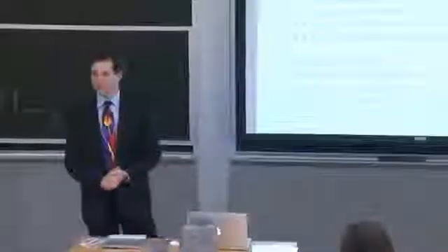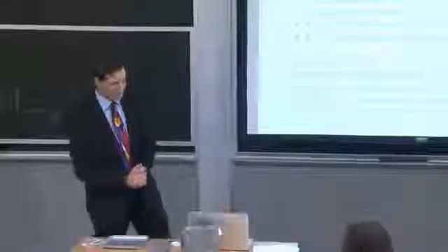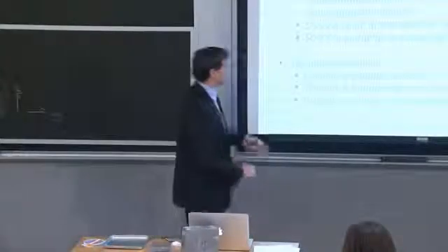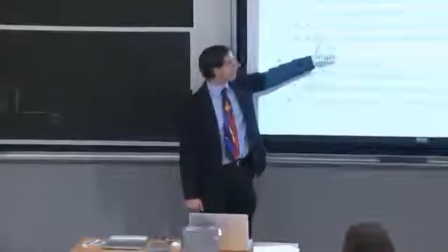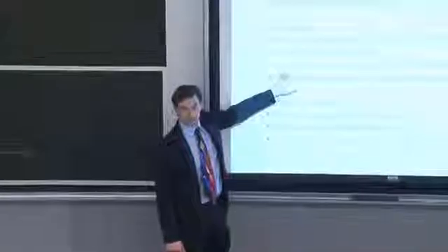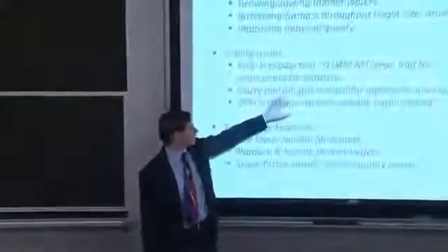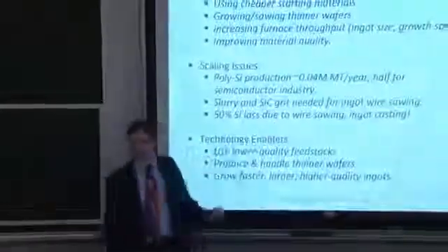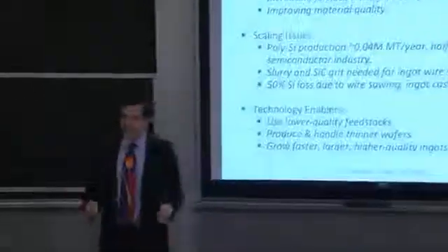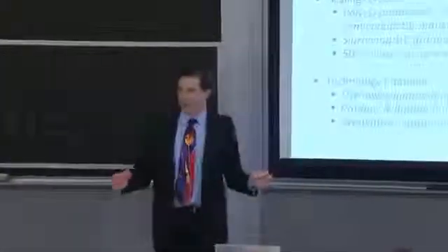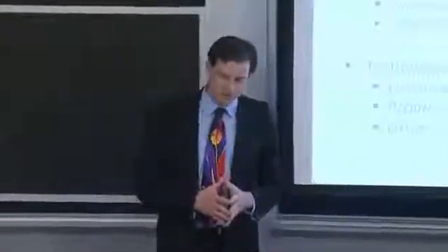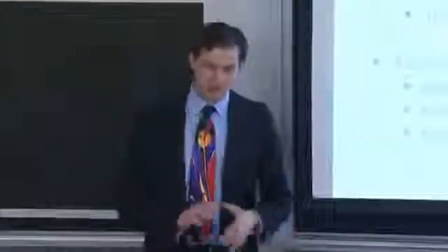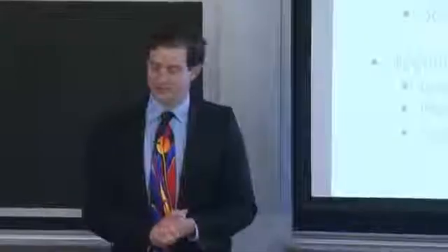Can the sawdust be collected and remelted again? Wonderful question. There was a lot of work done to try to figure that out. At that point, the sawdust is mixed with this glycol-based slurry and with the silicon carbide grit and with fragments of iron coming from the stainless steel wire, and nickel and chromium and other impurities inside of the wire. And so a lot of the work was focused on separation of those different constituents, shall we say.